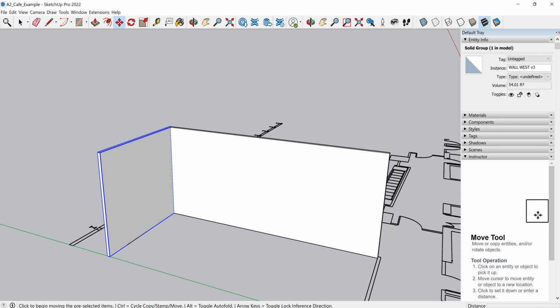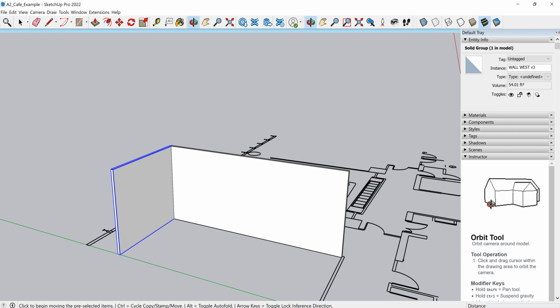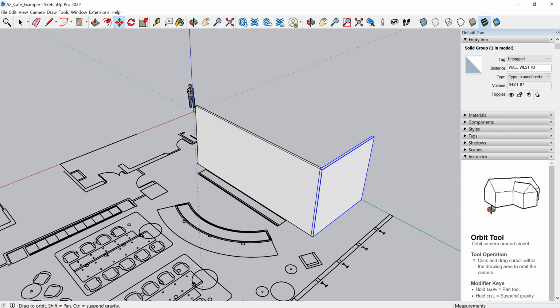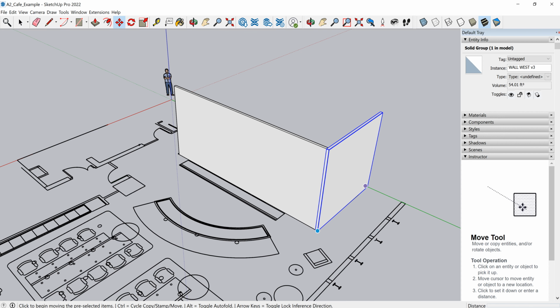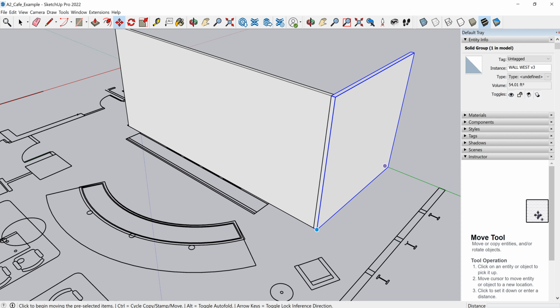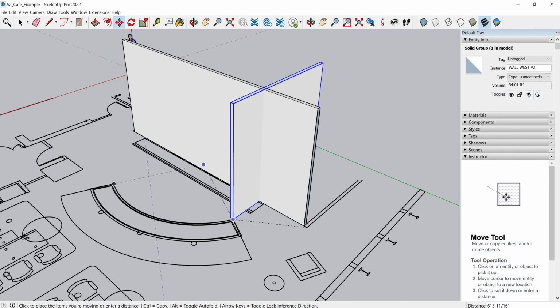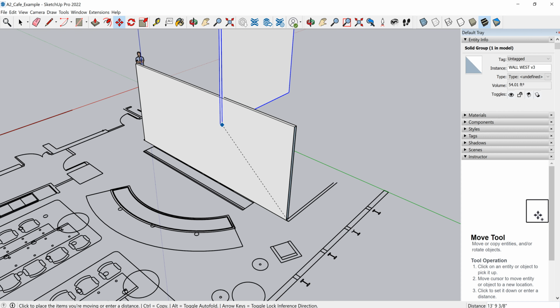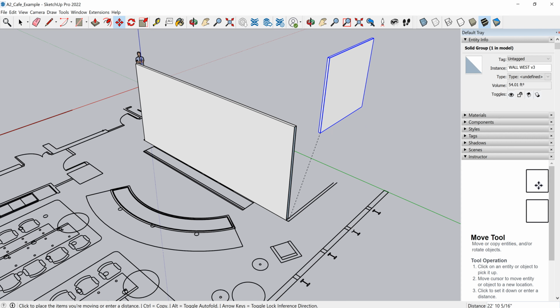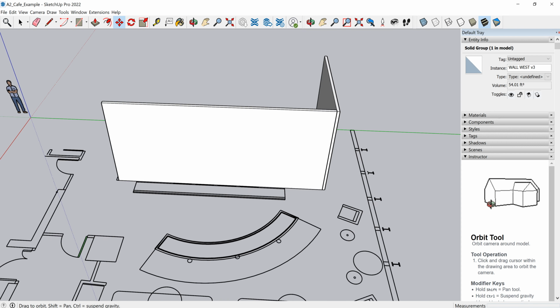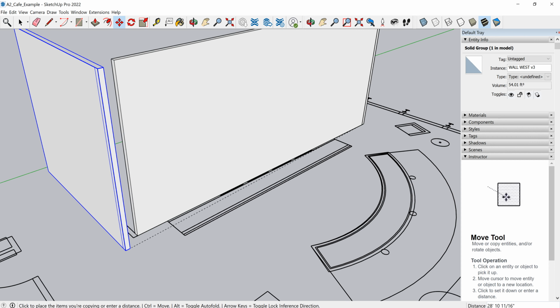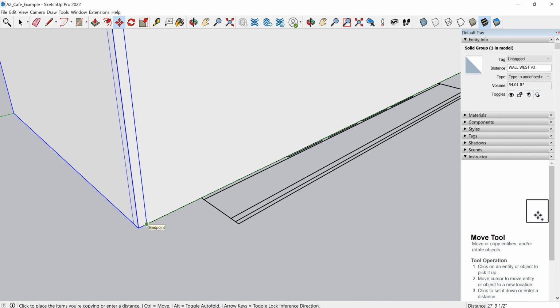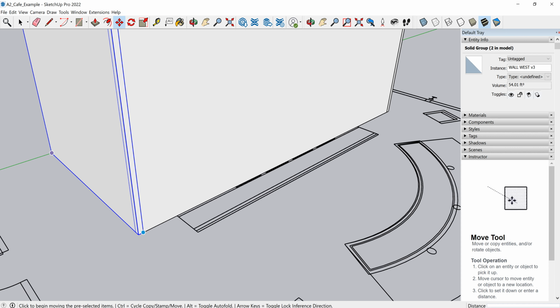I am going to select the object, and so where do I want to select it? I think it makes the most sense at this corner. So I'm going to copy it from this corner to that corner. So I'm going to select there. And when you go to Move, in the middle of Move, how you make the actual copy is you just select the Control key once, literally, bam. And then move into where you want to copy it and move into the actual point that matches the other side. And bam, bam.